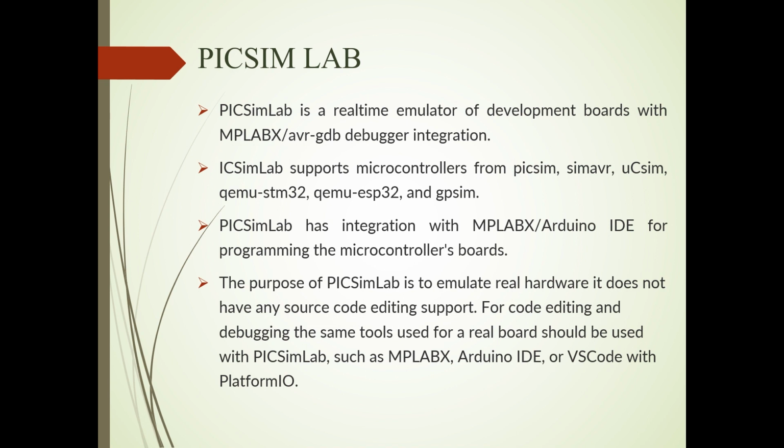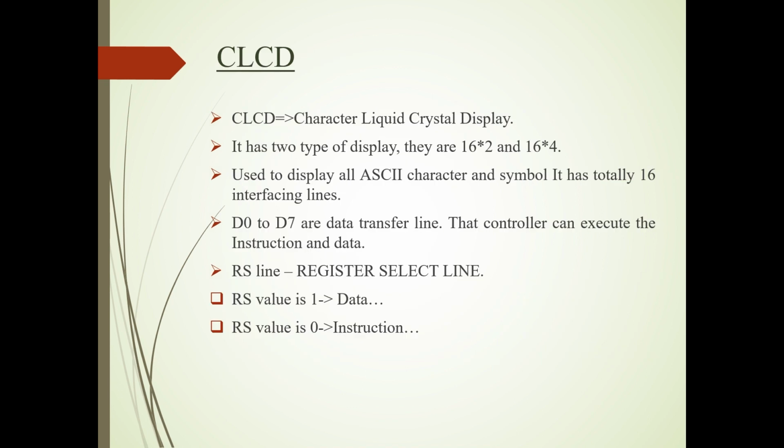The purpose of Proteus Lab is to emulate real-time hardware, as it does not have any source code editing support. So for code editing and debugging, the same tool used for a real board should be used with Proteus Lab, such as MPLABX, Arduino IDE, or VS Code with PlatformIO.